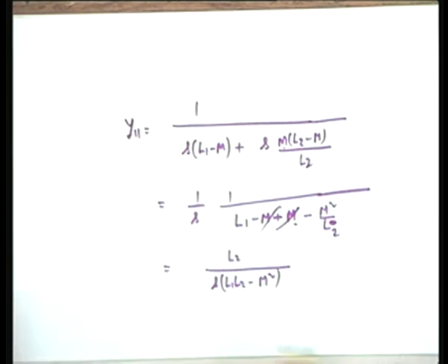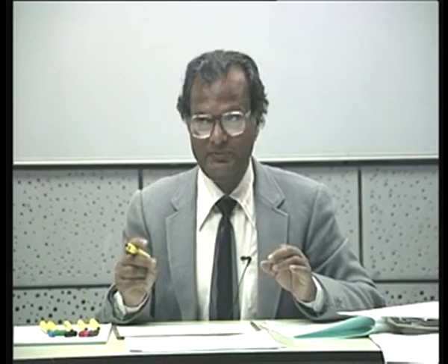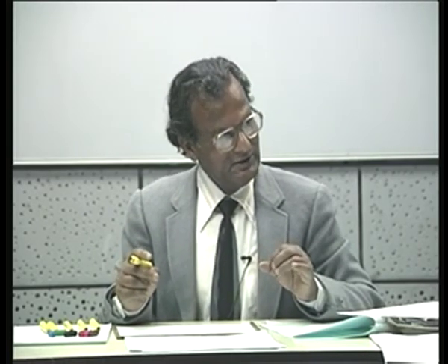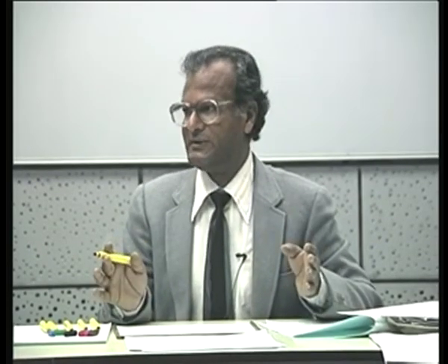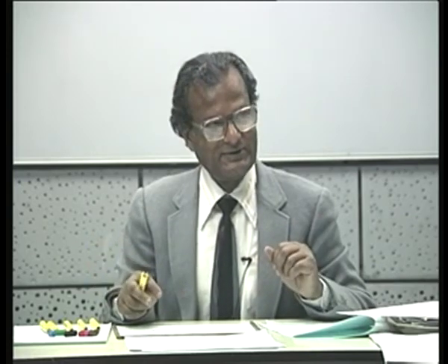Similarly, you can find the other two parameters, and I repeat, in this case you can apply the T equivalent circuit to derive the Y parameters, because it's your limited objective, but do not dare to do anything else, because you might destroy whatever your transformer and also whatever you connect to.